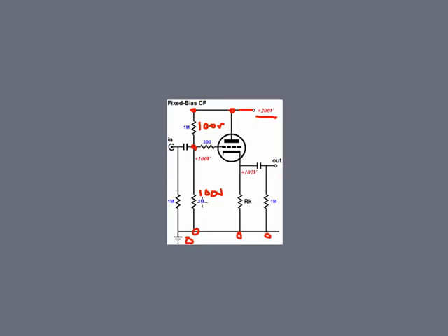If there's 100 volts across this resistor, then that point is the same as that. So that leaves this node on this schematic right here at 100 volts. And that's what it says. When the person was designing this circuit, they were very deliberate when they picked this resistor value and this resistor value, because what they were ultimately trying to do was create this 100 volts right here at this point. This is actually called biasing of this tube, and they intentionally picked these resistor values, used the voltage divider law to get to the point of voltage that they wanted right there at that spot.